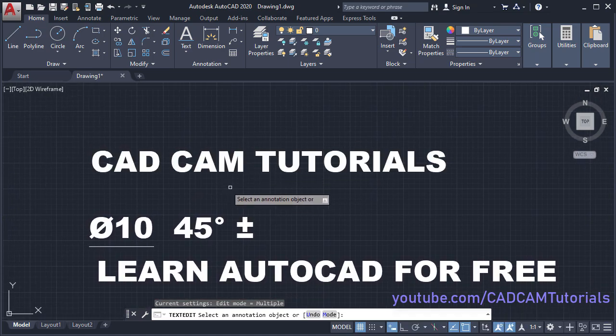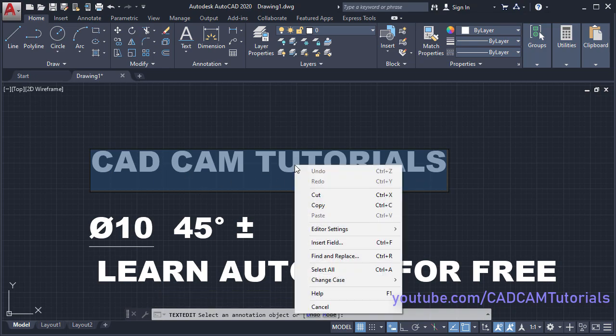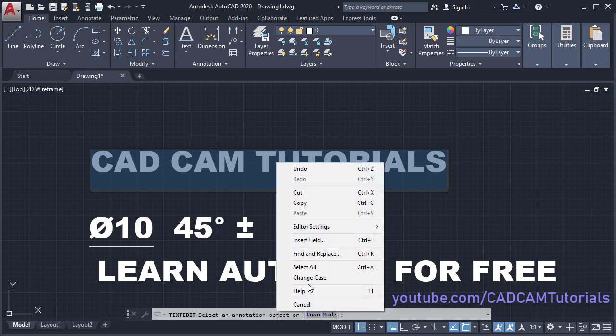Then if you want to change case of this text, so click on it. Then it is completely selected. If it is not, you will have to select it. Then right click. Take your cursor to change case, and from here you can make it lowercase or you can make it uppercase. And here keyboard shortcut is also shown, Ctrl Shift U or L. Then from this right click menu you can also insert field.